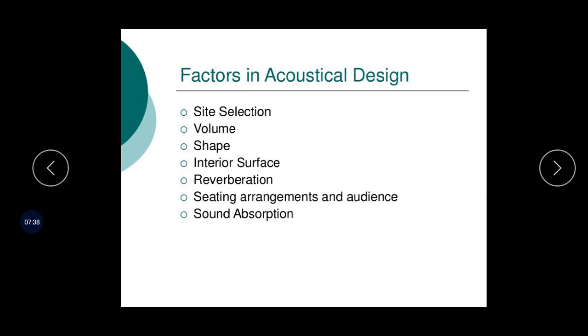The volume of a musical concert hall should be quite large so that sufficient space is available for proper distribution of music. In planning the volume of a hall, height is of greater importance than either length or breadth. Very important is height. We have to focus on height. We'll cover these values in the next slides also. If we are focusing on volume, for public lecture halls the volume per person is taken between 2.8 to 3.7 cubic meter.